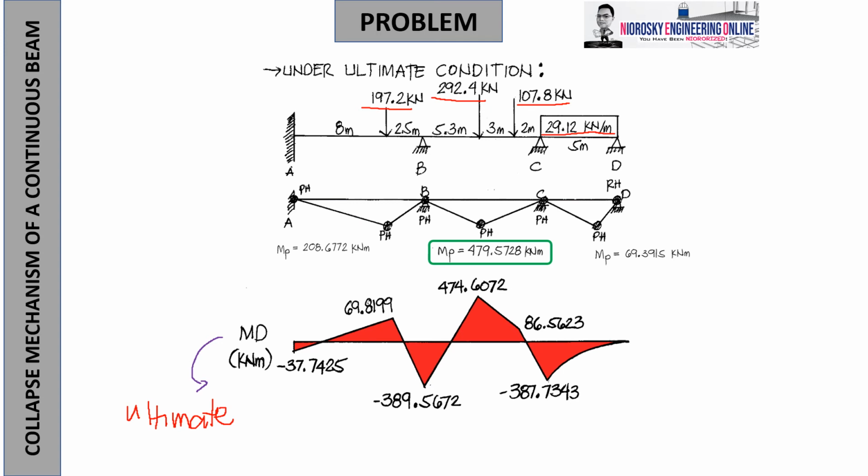Ngayon, if you want to get the nominal, just divide them by 0.9. Okay, just divide it by 0.9 here, 0.9 there, and all the loads, to get the nominal value. Pero, there's no need for us to get that kasi our main objective here is to compare, and of course we need to identify kung saan magsisimula ang hinging, then followed by the next points.